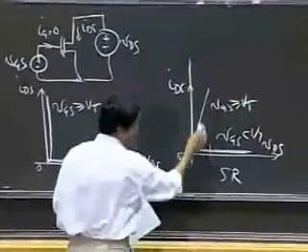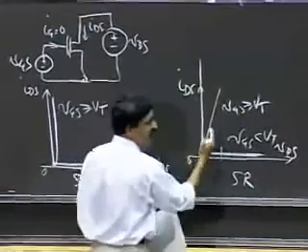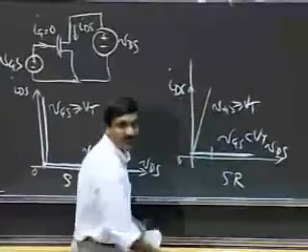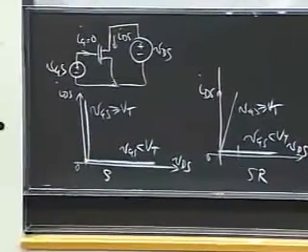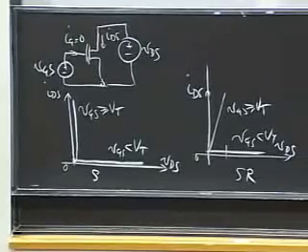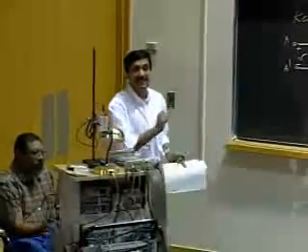Okay? Notice, it's for small values of VDS. I haven't told you what it looks like as VDS increases. Well, let's go try it out. We have a scope here. We have the MOSFET here. Now, I'm not sure what's going to happen. You may see smoke. We have an explosion. Who knows what. So just look up there for a second. I'm just going to increase VDS.